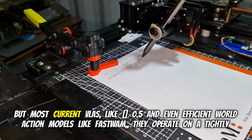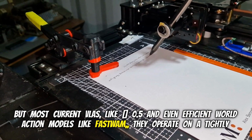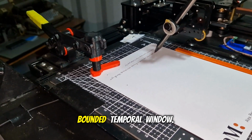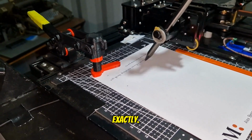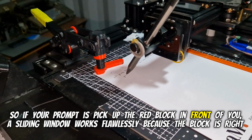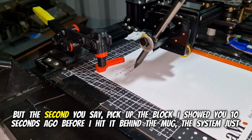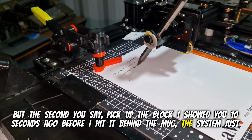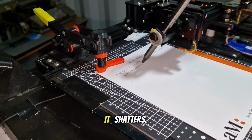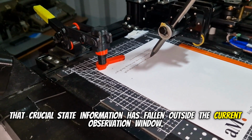Right. But most current VLAs, like Pi 0.5, and even efficient world action models like FastWAM, operate on a tightly bounded temporal window. They just map really recent observations directly to action? Exactly. So if your prompt is, pick up the red block in front of you, a sliding window works flawlessly because the block is right there. But the second you say, pick up the block I showed you 10 seconds ago before I hid it behind the mug, the system just breaks down. It shatters. That crucial state information has fallen outside the current observation window.